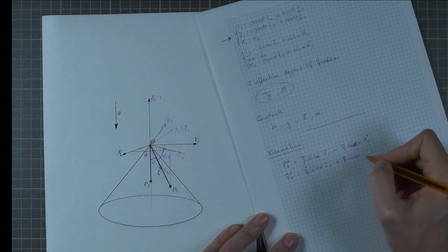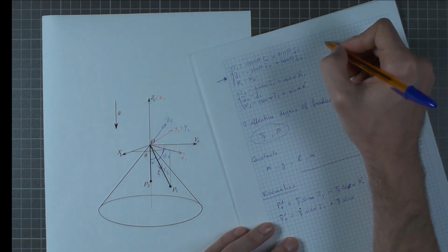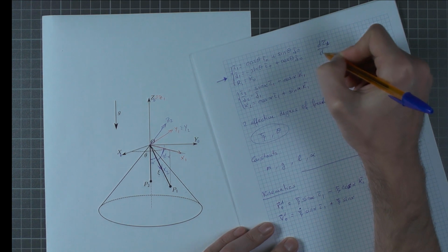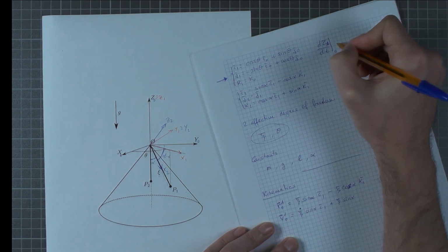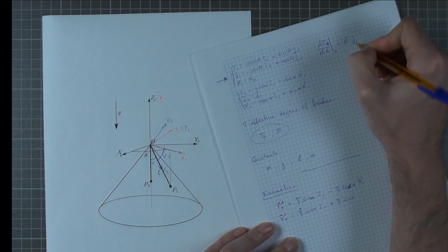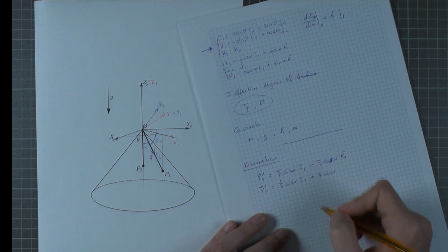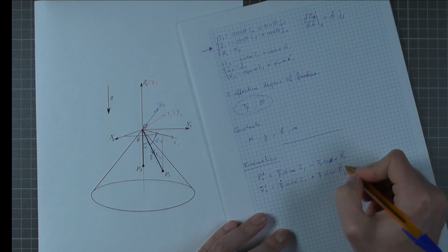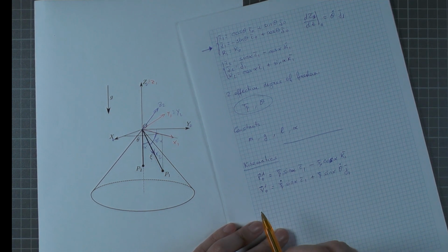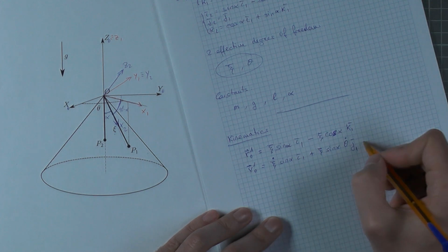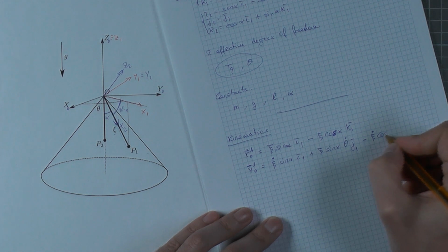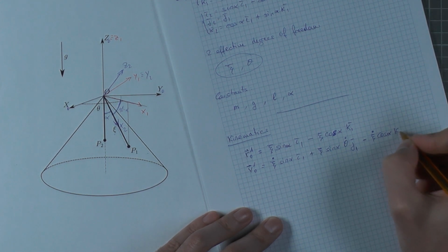If I did that, I could find that the derivative of I1 in time in reference frame 0 is equal to theta dot J1. That's very easy to prove. So we write that over here and we obtain this second term after applying the chain rule to the first term in the position. The second one over here just gives me one term, which is due to the derivative of h. Remember that alpha is a constant in this problem.